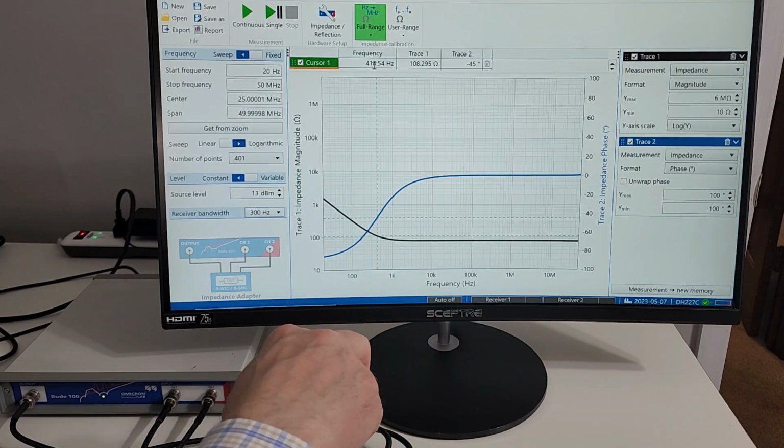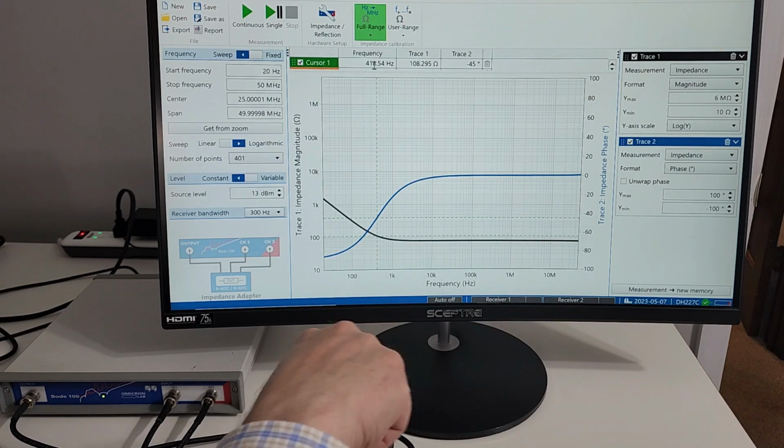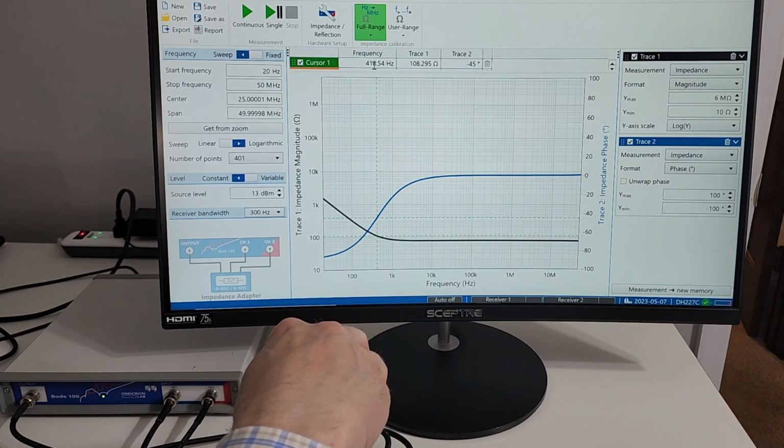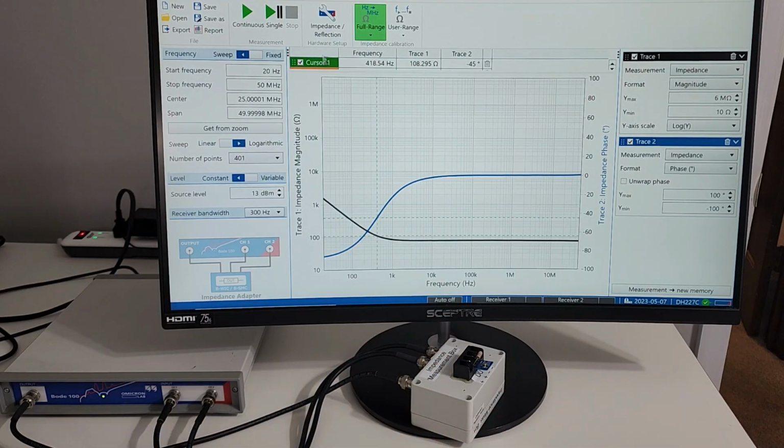So what I'm going to do is take that test board that has the series RC, and add in parallel the inductor, which is the series RL circuit, in parallel with the series RC of the capacitor. So there we have it. We'll run the impedance again. And notice what happens. My impedance is actually quite flat. If we measure the value here, it's around 75 ohms. The impedance is quite flat. My phase is pretty flat, around 0 degrees.